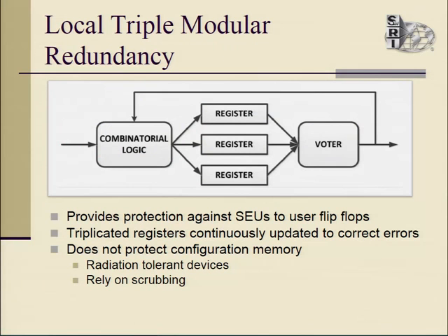Now, as I mentioned at the beginning, we also support generation in Verilog with triple modular redundancy. A couple of flavors of that, actually. The idea behind triple modular redundancy, or TMR, is to provide protection against single event upsets in FPGAs that are not radiation hardened. The way these manifest often is that the value of a user flip-flop will change, go from 0 to 1 or 1 to 0, without being meant to by the logic you've implemented.